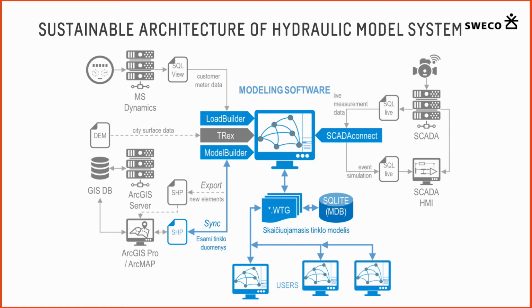And also a very important question when you talk about firefighting is real-time SCADA data integration. When you have a big fire, you can see the real situation in your model, and it also represents the real-time situation in your water network.